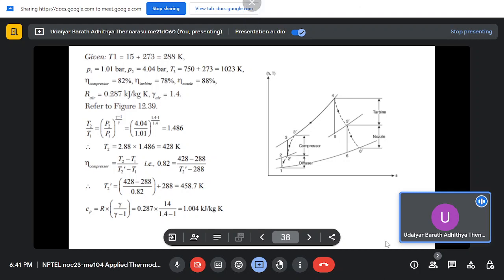Okay, the process will be somewhat similar to this. So you have initially diffuser. So from state 1 you are having some velocity, and then you are compressing it. So the velocity, kinetic energy is converted into pressure and it is brought to rest. So the velocity becomes 0. That's what it means. So state 2, that's what's happening in diffuser, and the diffuser has some efficiency, 90% efficiency.